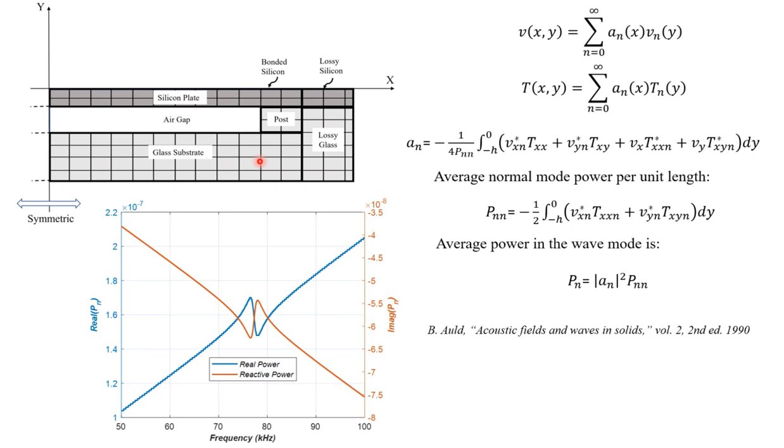And if you consider the longitudinal speed of sound in glass, that is about 5,600 meters per second, and that gives a wavelength of about 72 mm. So 72 mm, and if you compare 72 mm with a 0.5 mm glass, the thickness is negligible, nothing compared to the ultrasonic wavelength, because of the very high longitudinal speed of sound in the glass medium. So it's a case of a thin backing.